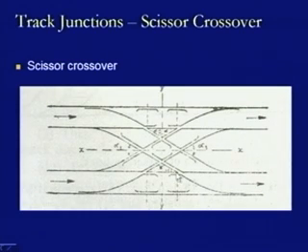So, here again what we found is that this is a wing rail extended, becomes a part of a diamond crossing, and again it becomes a wing rail on this side where another acute angle crossing is being provided. In the case of the obtuse angle crossing also, we found that there is one crossing in this location, one at this location. So, we have a wing rail here on this side as this side, but the other wing rail is becoming a part of the diamond crossing. So, we have a wing rail pair provided inside like this here, as well as this way here.